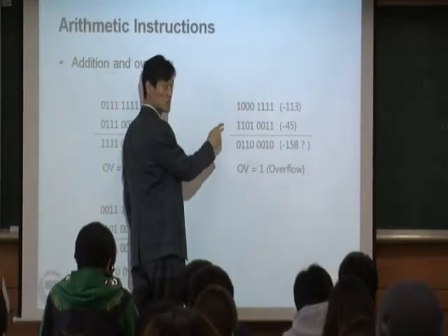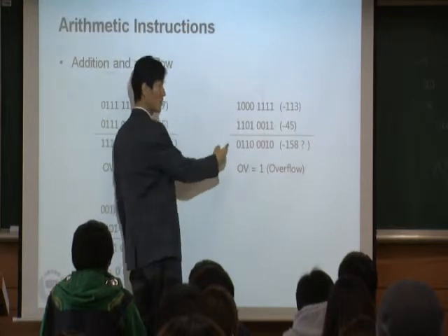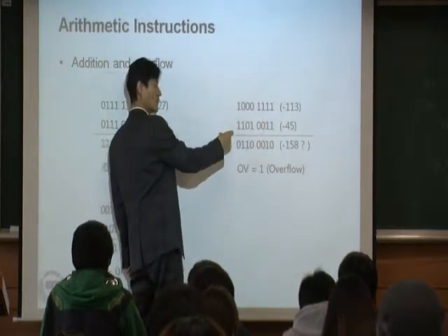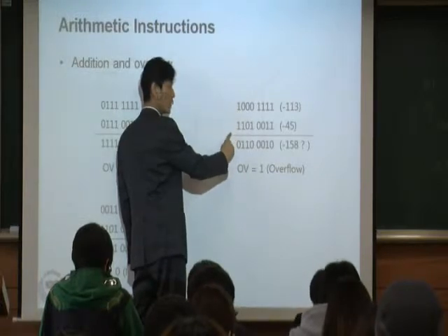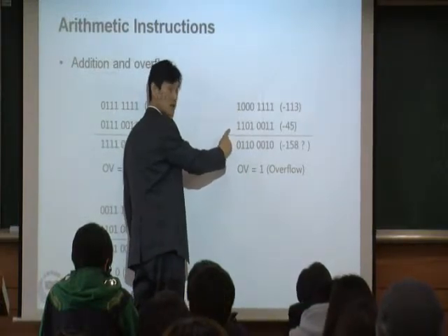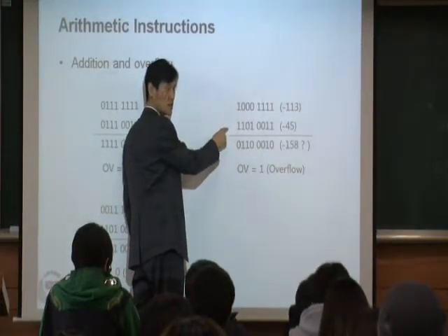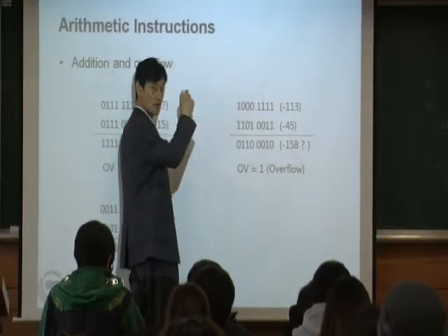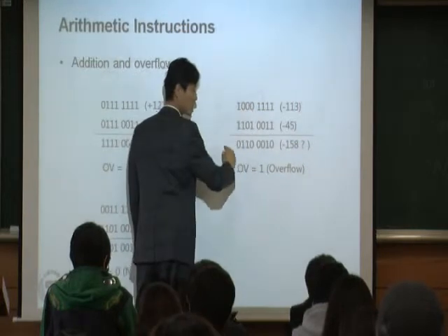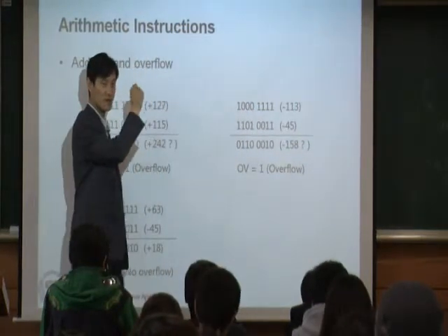What is this condition? This condition is a carry from bit 7. Think about it. When you add these two, 1, 1, you have a 1 in the 9th bit. So this is definitely a condition where you have a carry flag, because the result becomes 9 bits.